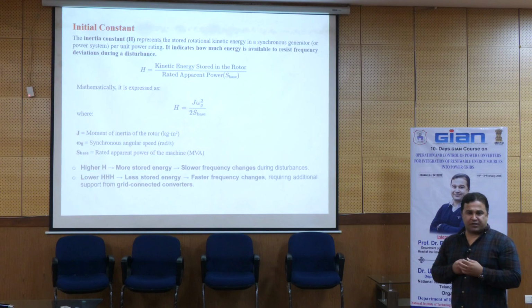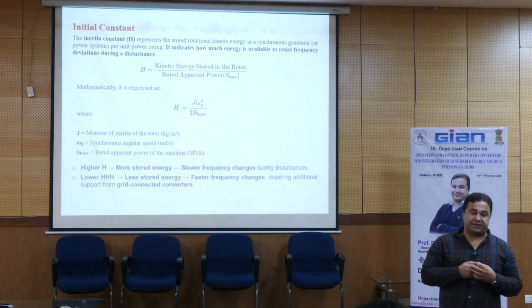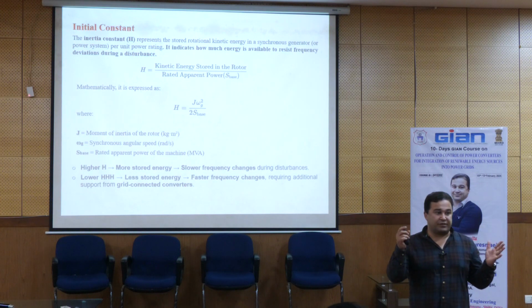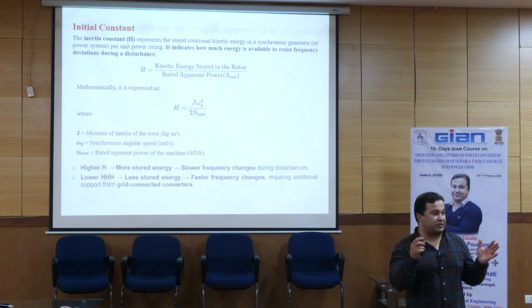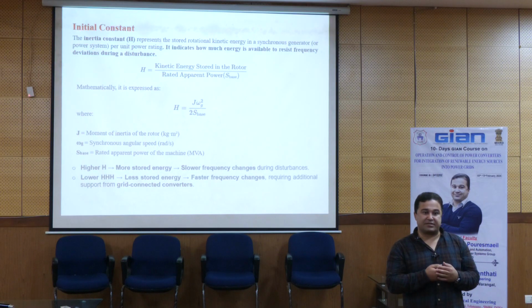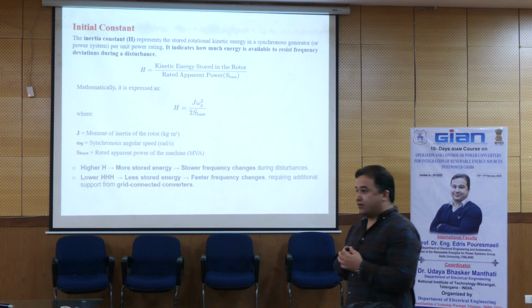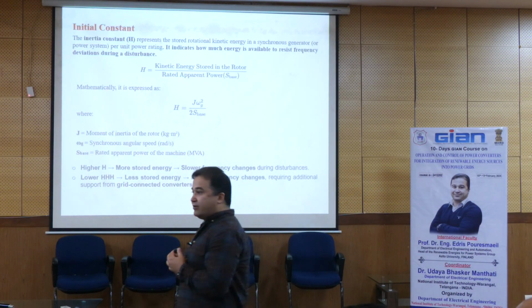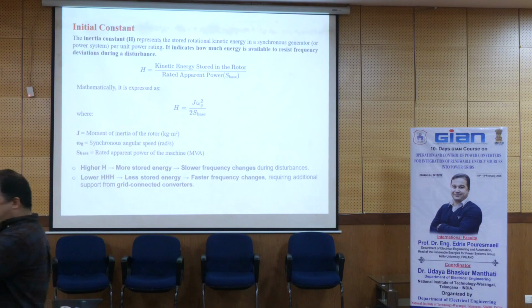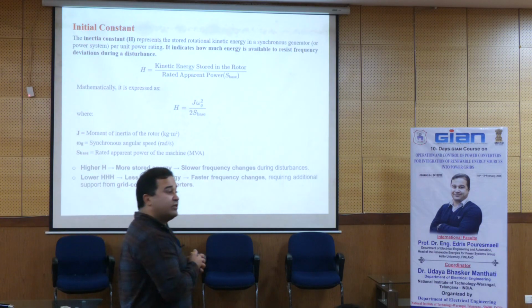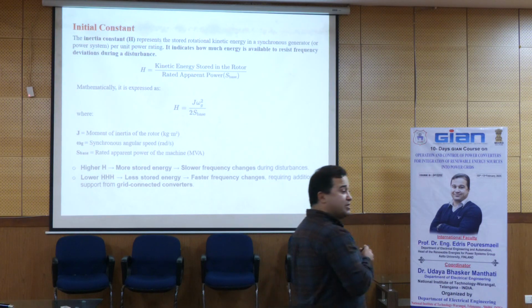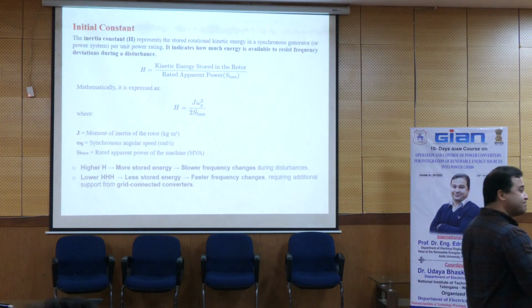So, question: do you believe that if H is bigger, our system is stronger, or when H is smaller, our system is stronger? Smaller, bigger. Why? Okay, great. So when H is bigger, it means that the kinetic energy in the power system is more.